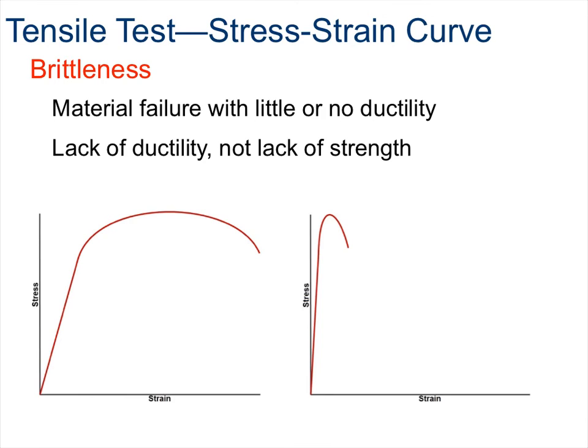Malleability is another mechanical property that is similar to the concept of ductility. A malleable material is able to resist change in shape under applied compressive loads without breaking. Therefore, malleability is a mechanical property that allows a material to experience plastic deformation through compression without breaking. The most common example is pounding or rolling a material into the shape of a thin sheet. Gold, copper, and aluminum are naturally malleable materials.